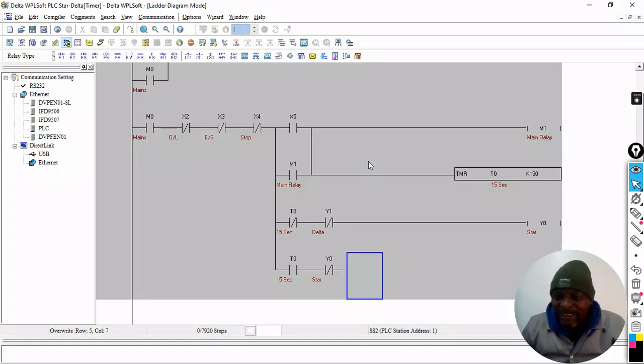Relays are very gentle and need very low current situations, and contactors prefer the heavier current situations. But electrically, they are the same. It's a coil, what we call an electromagnetic switch. A coil that is controlling some switches. So both of them are electrically the same.